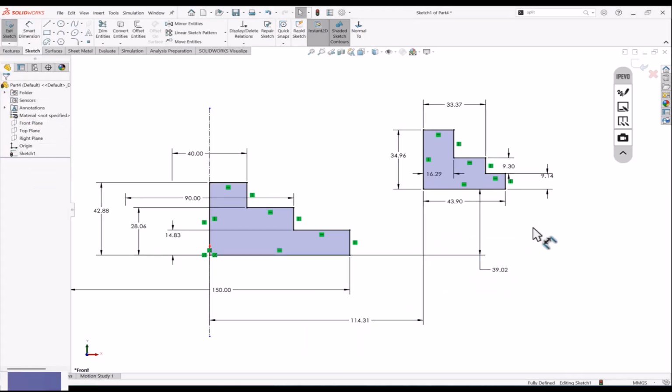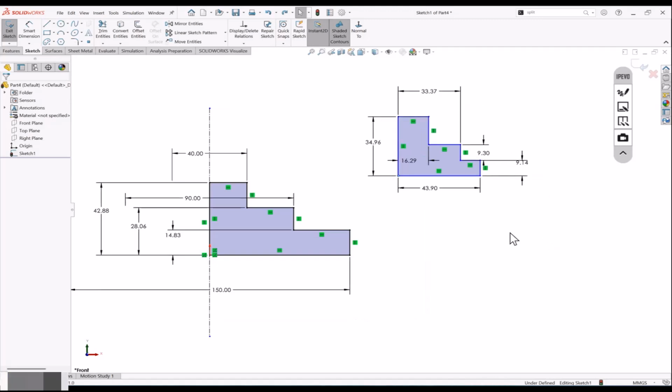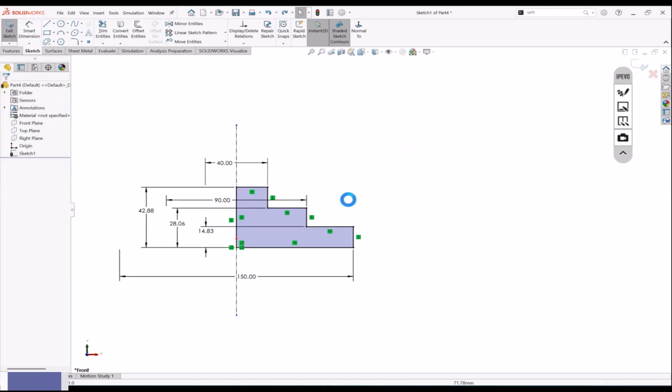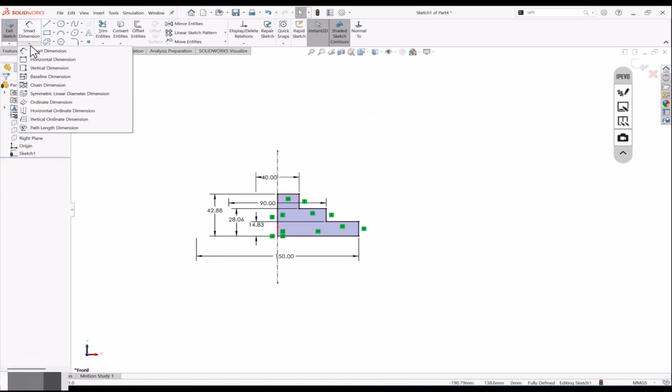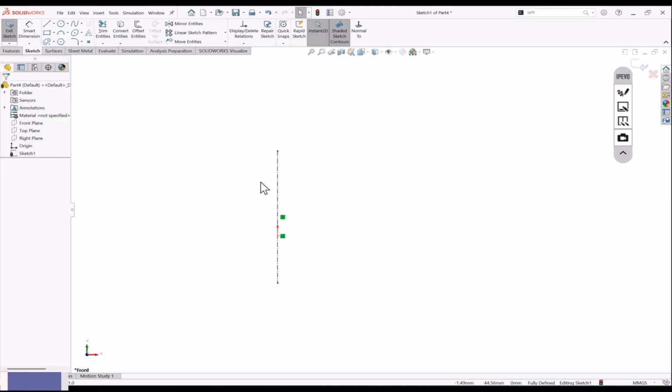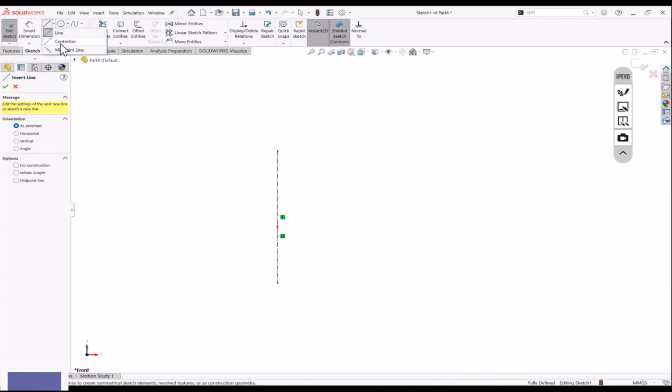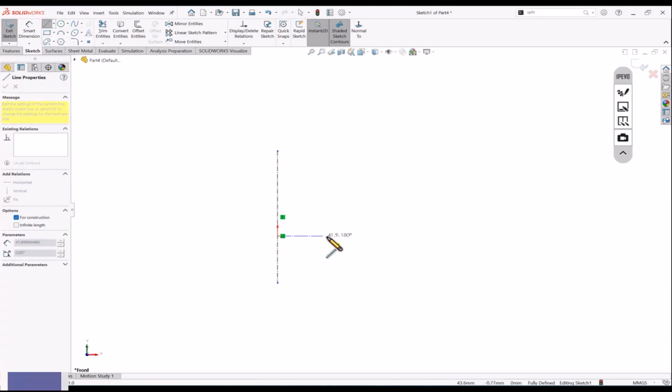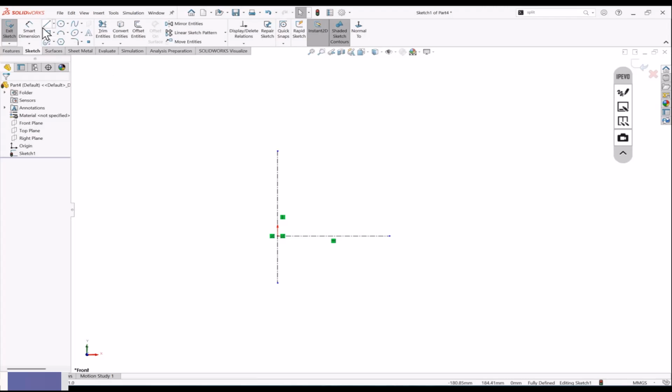Okay. So that's why the origin is very important to define your objects. Now let's see other dimensions. So we have ordinate dimension. Ordinate means to find out the coordinate value for any objects that you have. Let's create something and we'll randomly draw and calculate the coordinate for that part.